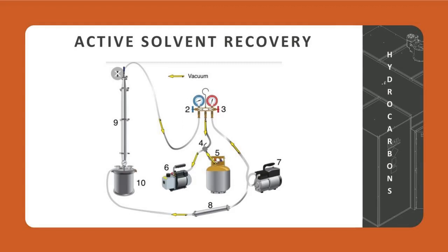I do want to say, because there's always a little bit of safety thrown into our webinars here, very specific types of pumps are required for this. You do not want to use a typical vacuum pump that is either electronic or mechanical. Instead, you want to use a pneumatic pump that has no capabilities to spark or actually ignite the hydrocarbons that pass through it. A little bit more expensive, but if your goal is to have the most efficient process and have the highest throughput possible for your closed-loop system, the cost will be nominal to the eventual gains you get through that increased processing capability.